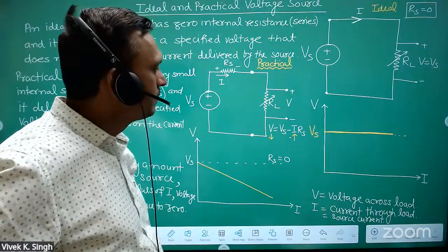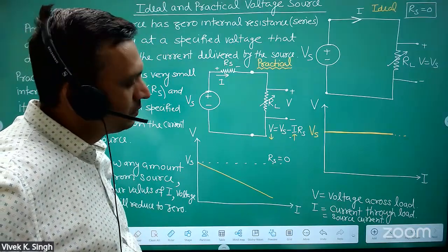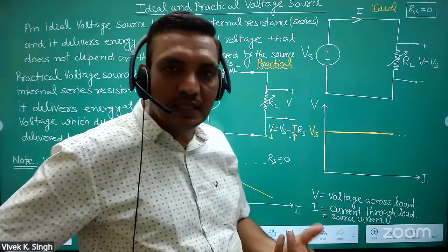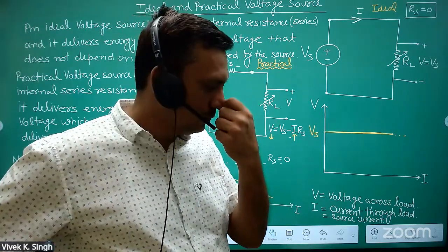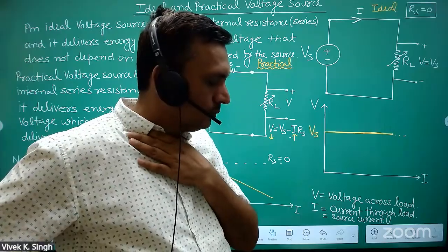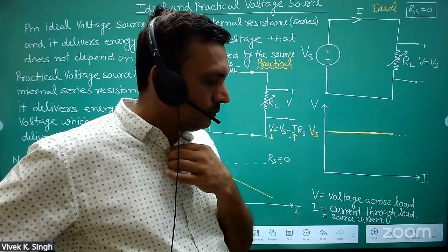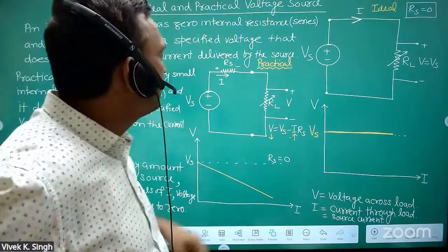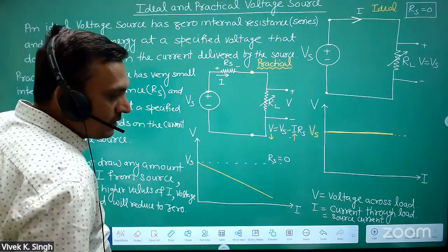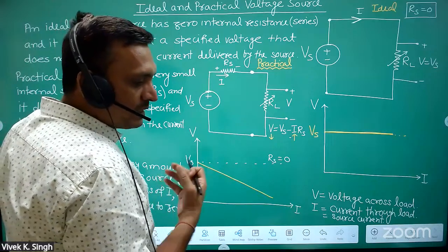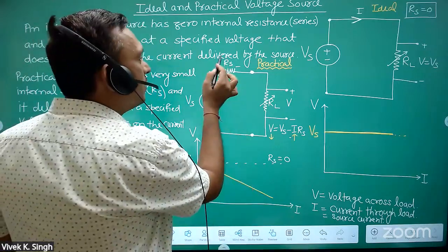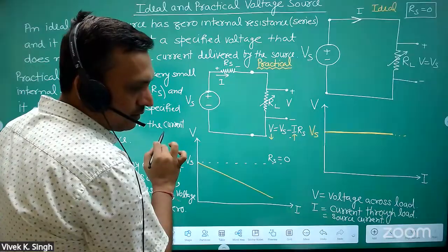Load decreases means that load resistance decreases. Yes, load resistance decreases. Sir, in that situation, what is the purpose of the RS? No, this RS is fixed. This is the source resistance. You can't change this. When you design some voltage source, there will be some fixed source resistance.